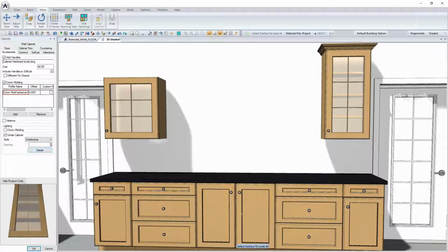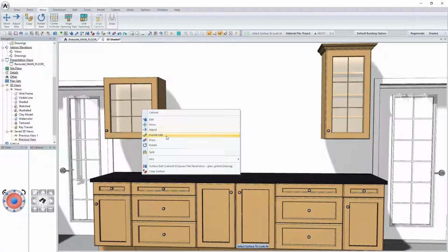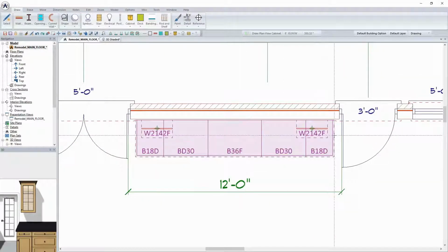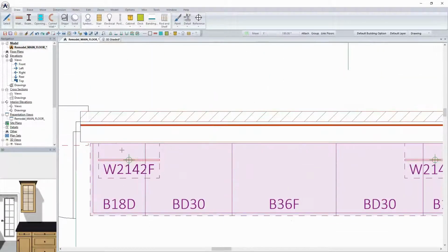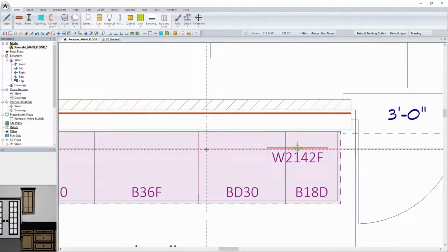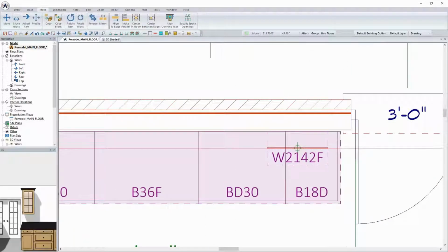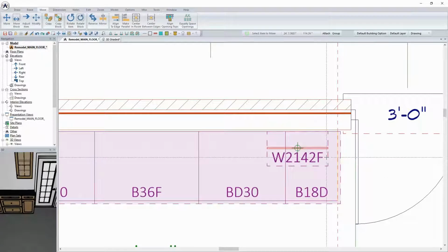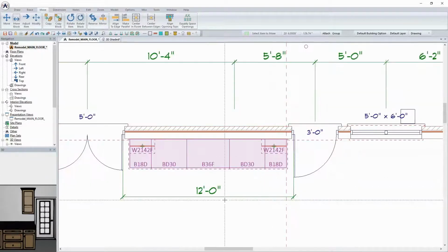So all of that can be set up, and once I've done that, I'm going to repeat edit that same change over there. The plan view is probably where I'm going to do most of this type of thing where I'm just moving it to a line, and I could even use the move and align to edge, which is to say I can pick the edge of the cabinet and pick the edge of the cabinet and move it into place. Something like so.